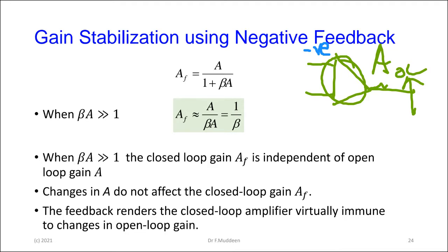And with negative feedback, we derived this little relationship that we did, must be about 6 or 7 times by now. So the open loop gain, which is A, if you put it now into our feedback network, the overall feedback gain is A over 1 plus A beta. Beta, of course, is the gain of the feedback network.